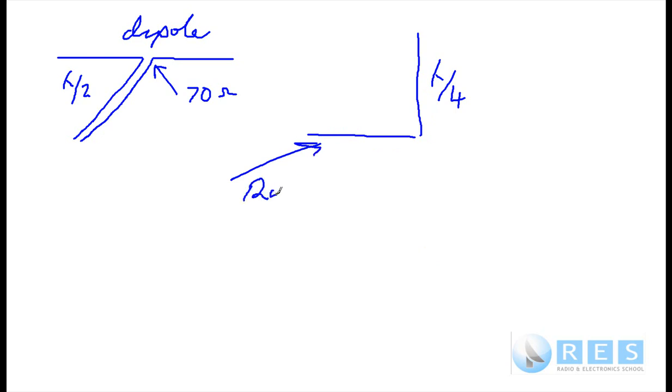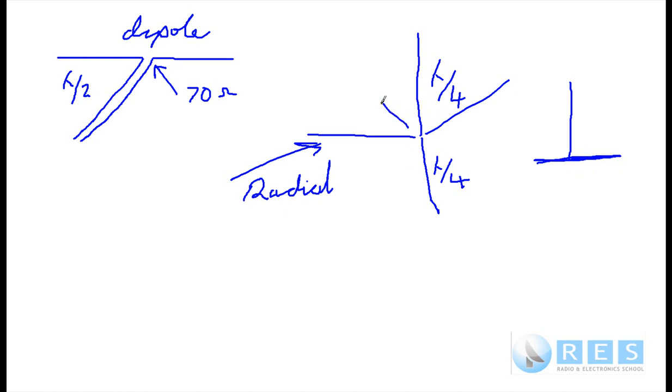And normally we put at least 3 radials or more on a vertical ground plane antenna. So we'd have another radial coming out here, another radial going out there, and if you look side on you'd only see that. And they're all a quarter wavelength long, and they're horizontal. I'm a bad drawer, so it doesn't look horizontal, but this is a side elevation, and they're all horizontal. If we do that with a quarter wave ground plane antenna, the impedance there is around about half that of a dipole. That's no surprise, is it?